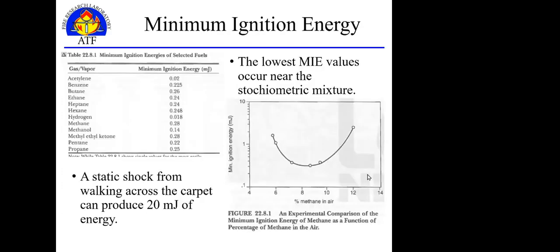The minimum ignition energy figures on the table came out of the 2021 edition of 921, so you can see where the minimum ignition energies are. Again, natural gas is primarily methane, so that's where we typically pull its properties from.